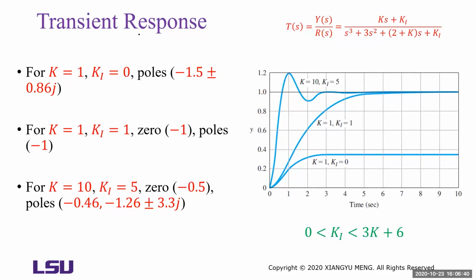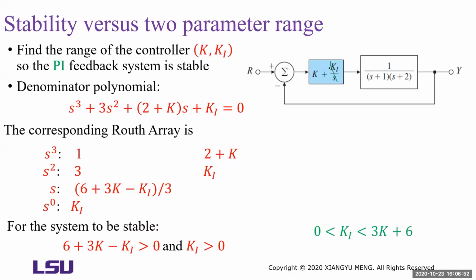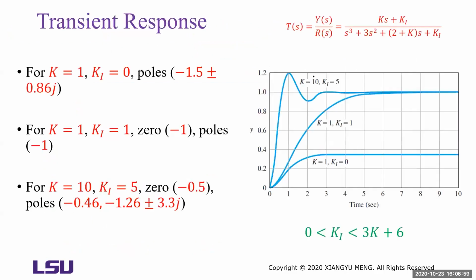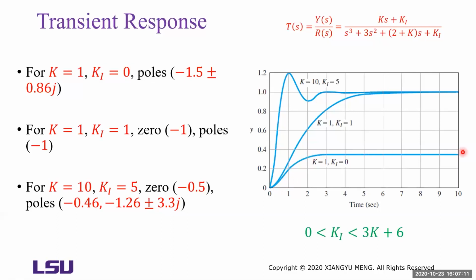First, let's use the proportional control only. Let the integral part be 0. That is, we let ki be 0. We only use the proportional control. And here it shows the step response. If the input signal is a step signal, this line shows the step response.